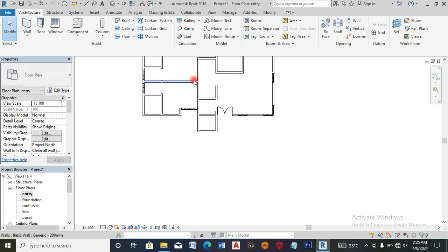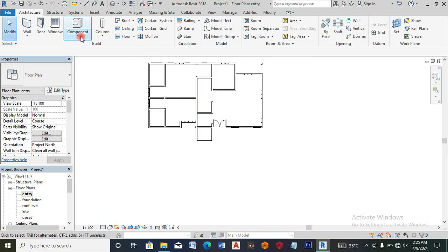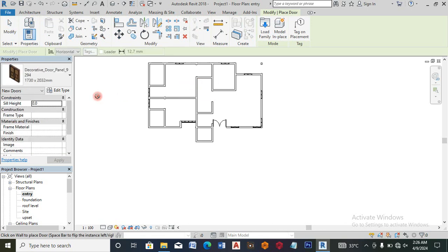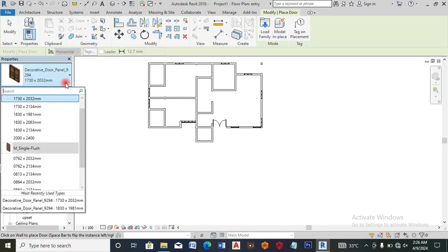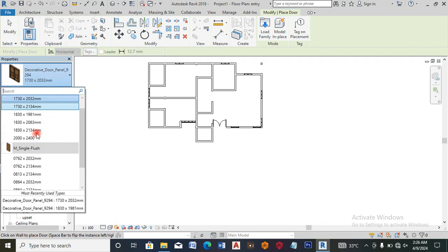Now the next thing I'll be fixing is my bedroom doors. Door 900. I still go back to door. Or you can actually check from your defaults if there are doors that you can use. The doors 700, 800. So let's use this one and try to edit. Let's click on one of the doors and try to edit.